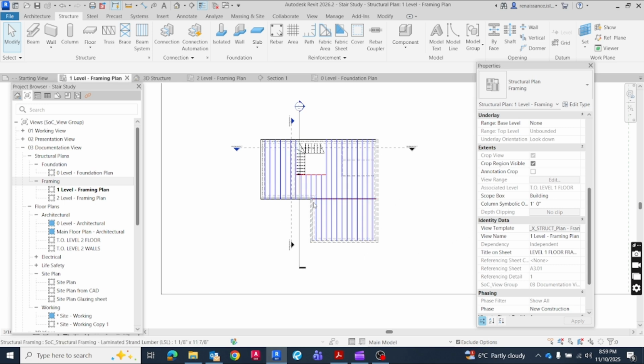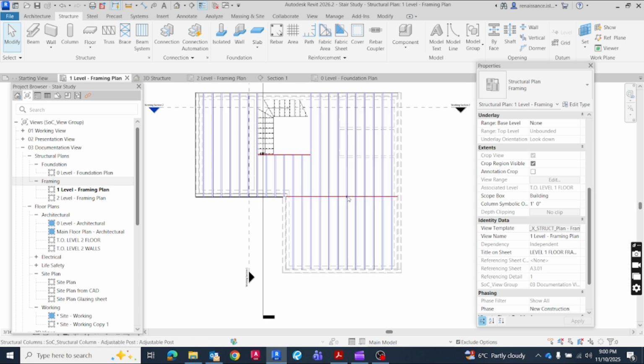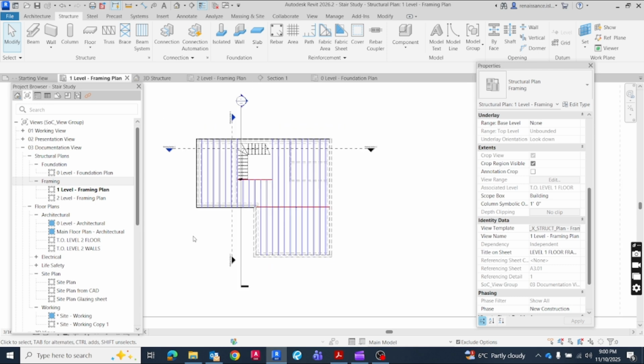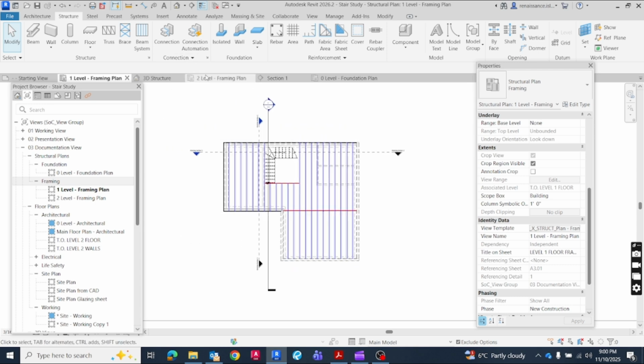It's not fully completed, because I just showed the rim joist and the joists over there, the beams, and then we have some posts. So we need to complete that with the rim joist all around here and the joist here. And then maybe you need beams or another double joist, so you can insert them the same way. The process is the same. Now let's go to level 2, because I already have level 1 done.